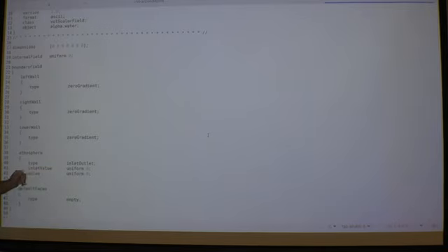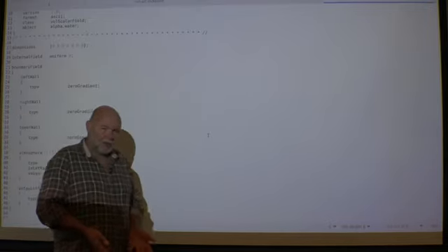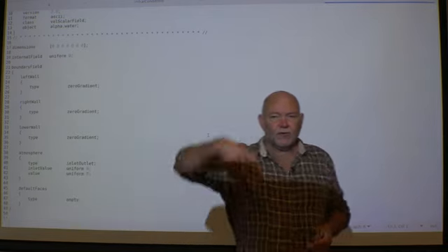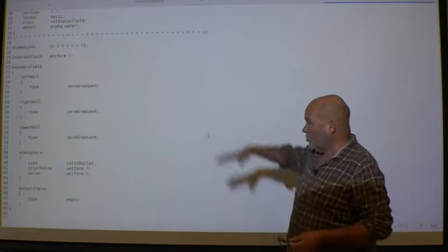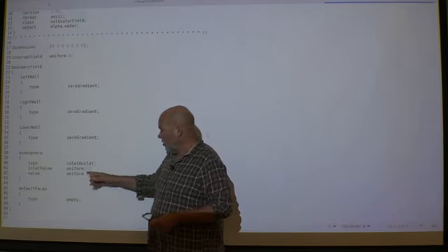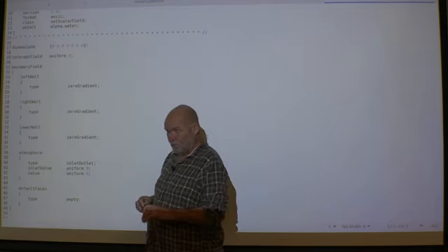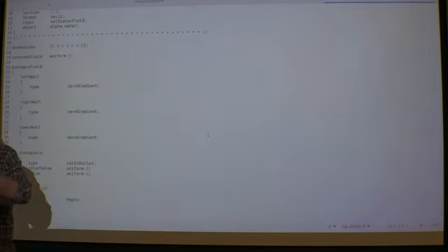So if it goes out, so be it. But if it comes in, then you have to specify what's supposed to come in. So here, this alpha variable may be pushed up through the ceiling, into the atmosphere. But it's incompressible, so if something goes out, then something has to come in another place. And what's coming in? Alpha equals 0, meaning only air. So if you have some water splashing and going through the top, it's going to disappear into the unknown, into the atmosphere, and we will get air back. Of course, you could have changed this to 1, and then it would be water coming in. Might be a little bit weird. You'll see when we start this simulation here.